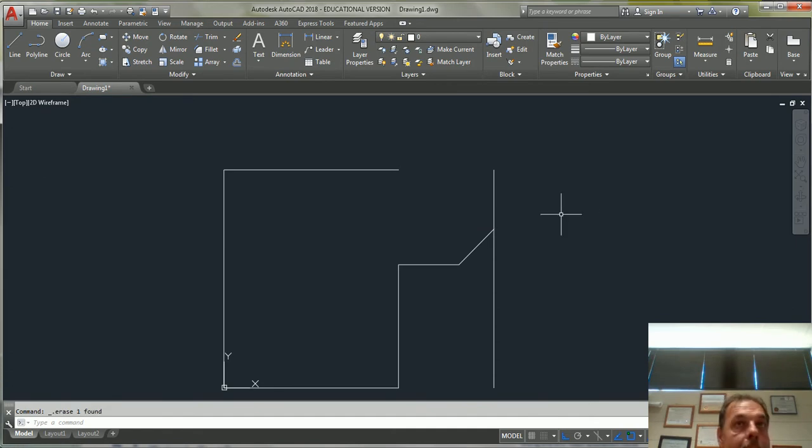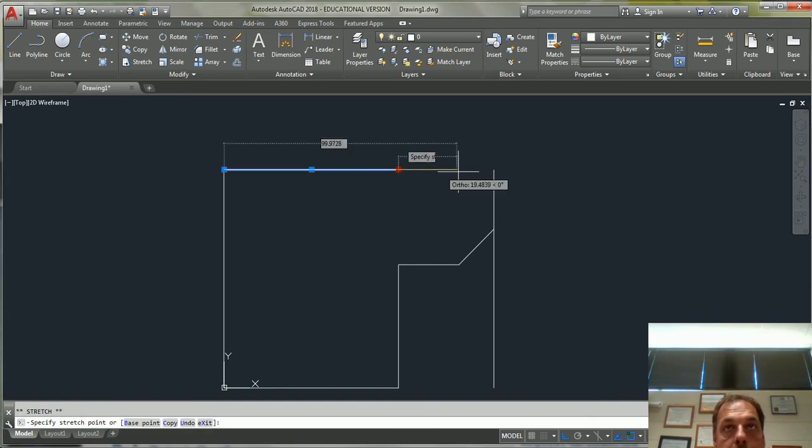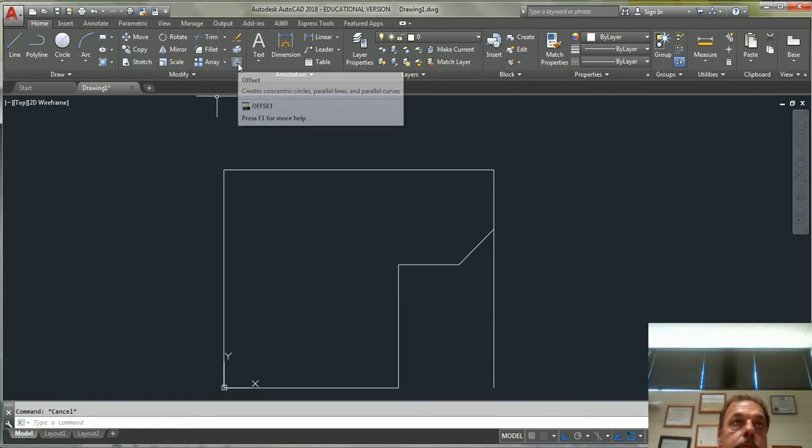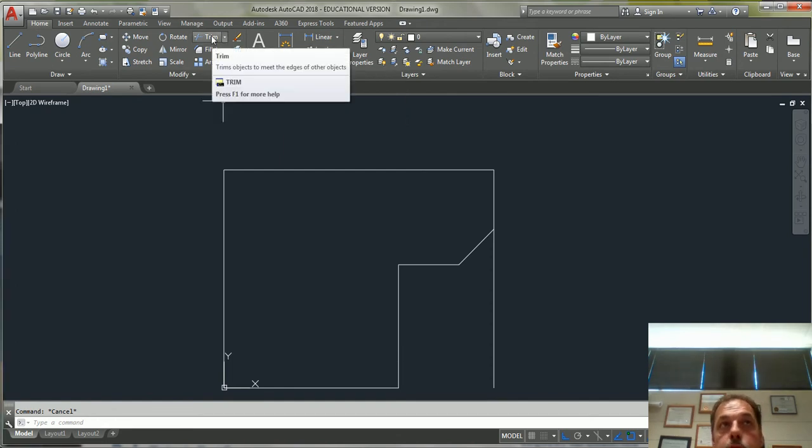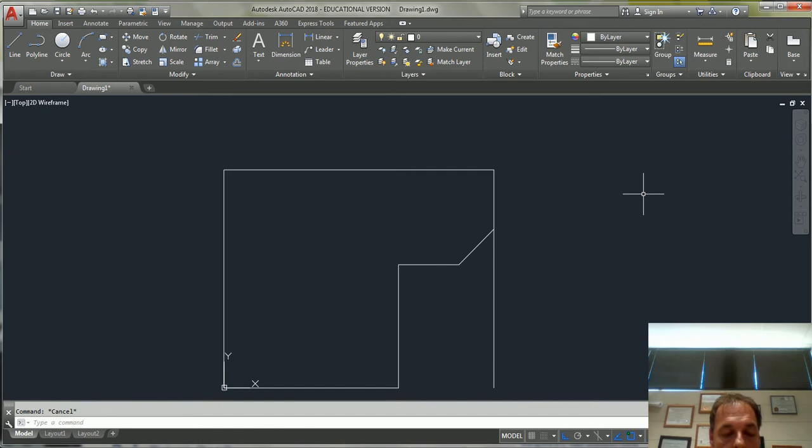Now I'm going to go ahead and bring this on over by clicking on that button and snapping it. Okay, so we've learned offset. Offset's also right here, guys; you can click on it there. There's another thing called trim. I'm going to teach you really quick. You type TR, enter, enter, and watch as I trim that geometry. Boom.